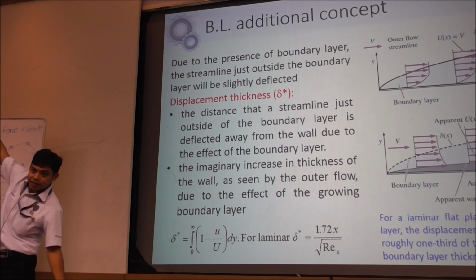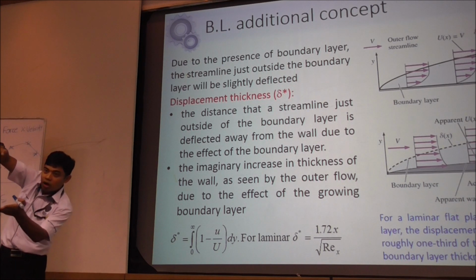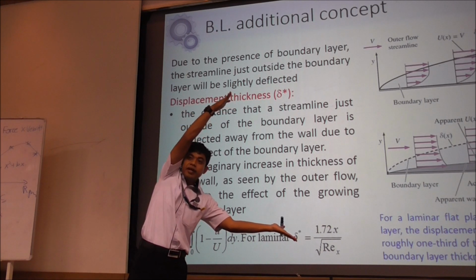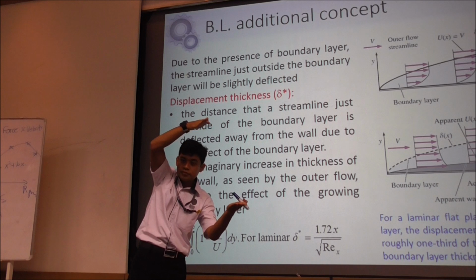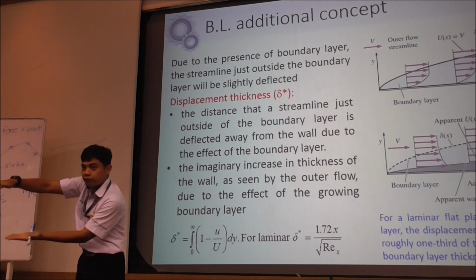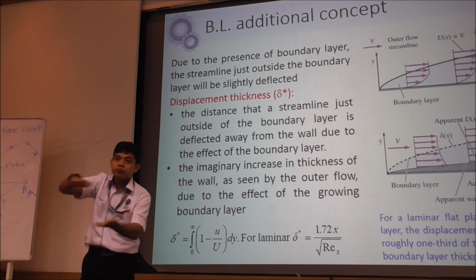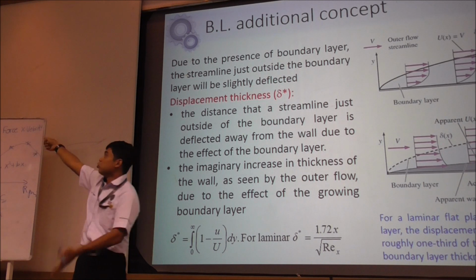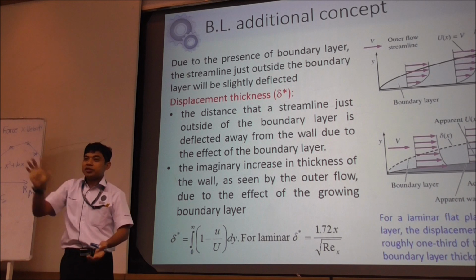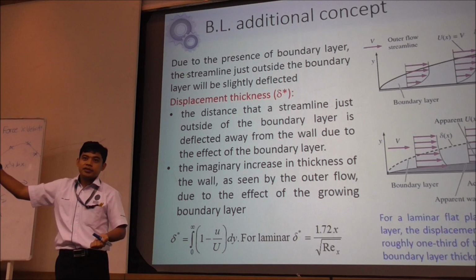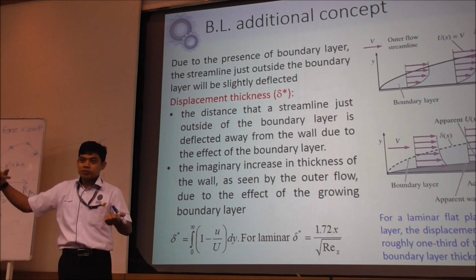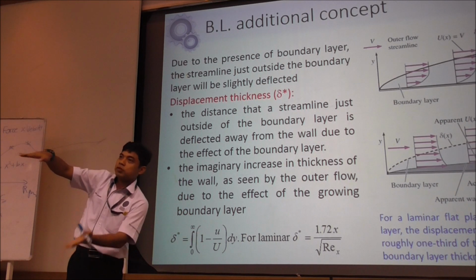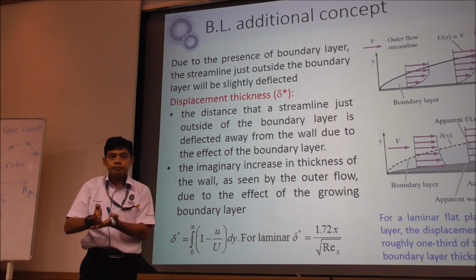You have a big tunnel, then it becomes small, goes into that, and expands again. There is a reason why you do that. Because you want to get the flow to be uniform. You want to mimic the uniformness of that. That's why you have those big sections. It is not there just for fun. It is there to help the flow with the profile.